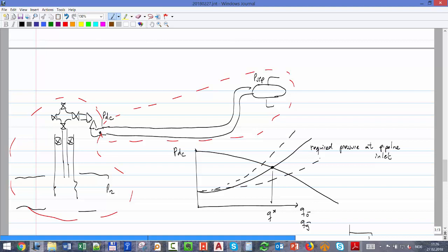You can change or modify the choke. Yeah. But we are now looking at a system where the choke is not included. It's in the other system, in the curve that looks like that. That curve will change with the GR as well. This curve will change with, let's say, the diameter. If I use phi1, phi2, and phi3, and phi1 is smaller than phi2, smaller than phi3, then I can move the point to the left, right?